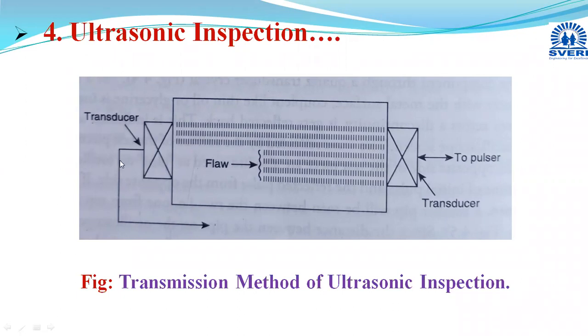Okay, due to this, whichever signal is generated at the CRO screen will be a weak and disturbed signal. Depending on that weak and disturbed signal, we can say that a flaw or defect is present, and with the help of the respective time calculation, we can determine the location of that flaw.